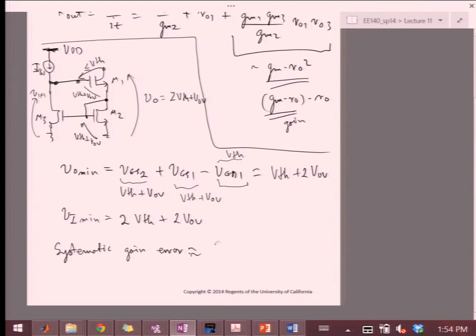We know it's going to be lambda, right? Because it comes from channel length modulation. It's going to be the same exact kind of ratioing of wherever our diode transistor is, which is diode connected, which sort of maps the current and serves as a reference. In this case, that's M2. And the other transistor, right? Which is the one that kind of controls the output, and that's M3. Right?